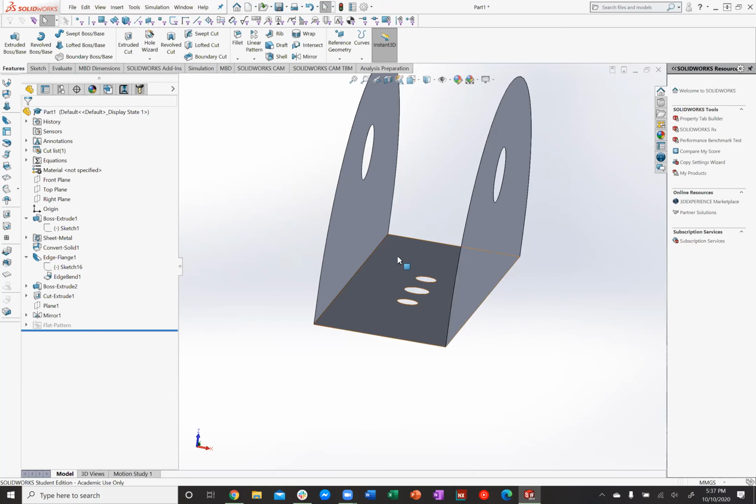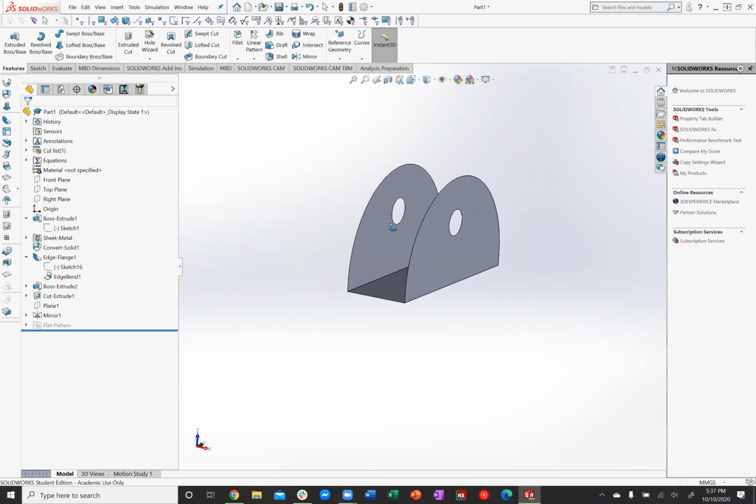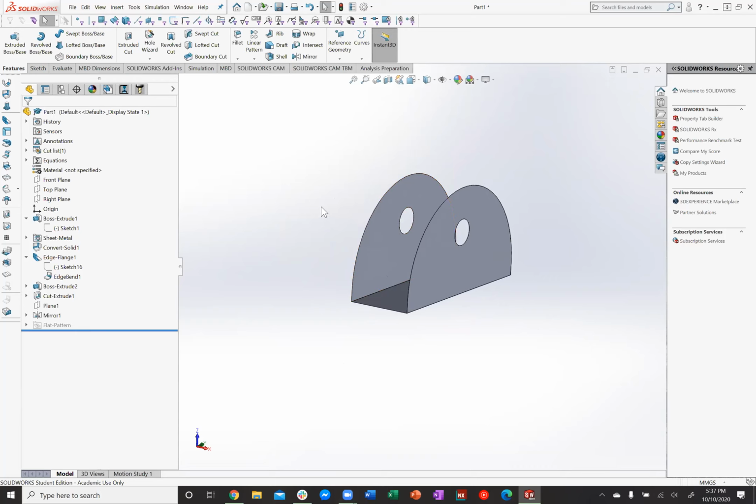Theoretically that works, but I think there's a better way to do that. So instead of using a coining method, you can use either the air bend or that bending tool that we have in the shop by adding a piece of flat material to the outside of this that's temporary and breaks away.